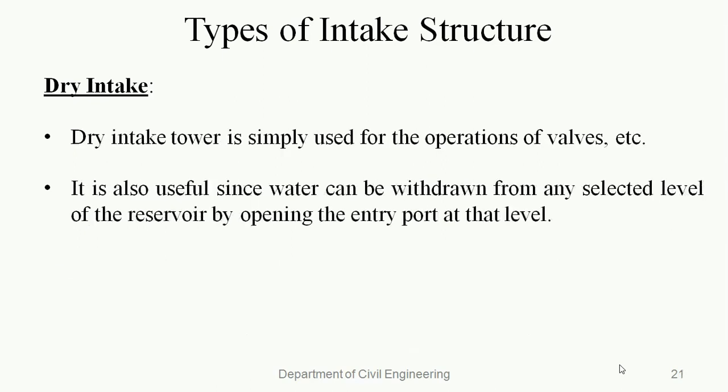A dry intake tower is simply used for the operation of gates and valves which control the flow of water into the withdrawal conduit. It is also useful since water can be withdrawn from any selected level of the reservoir by opening the entry port present at that particular level.